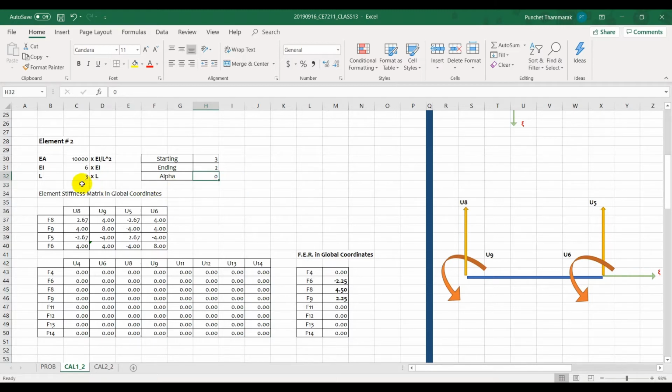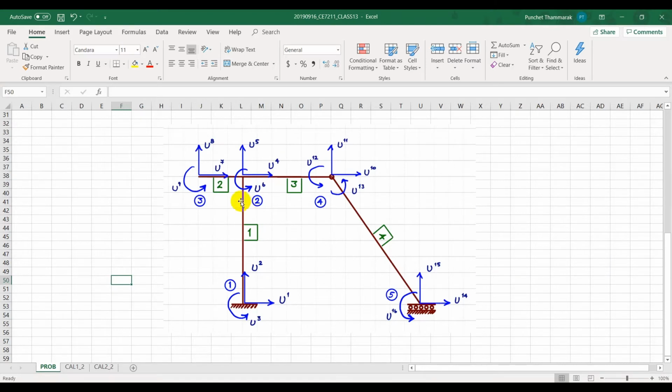this calculation. The EA was set to be a large number, so it is huge compared with the bending rigidity, but anyway, we are not using this EA in this calculation because we are saying that the degrees of freedom number 4, number 7 and number 10, which are along these beam members, cannot stretch or compress.